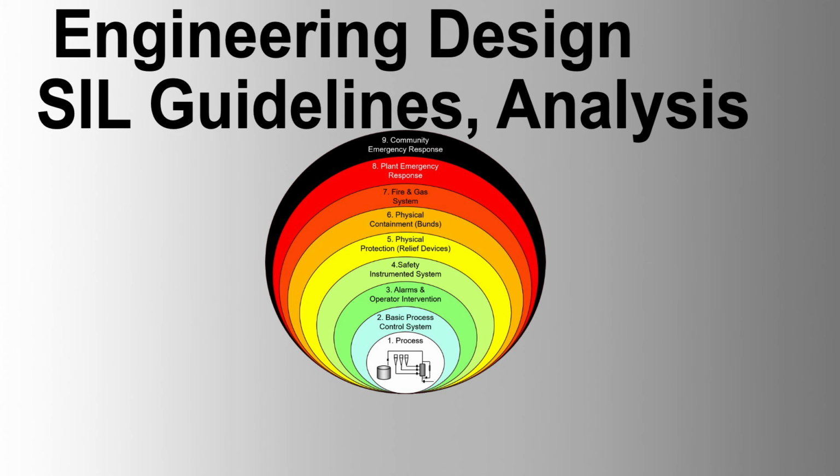5. Quantitative evaluation of fault tree. Use failure rate data to quantify the fault tree. This involves using Boolean algebra to calculate the PFD and the MTTF spurious. Conservative failure rates should be used for SIS components to ensure a higher estimate of PFD. Generate a cut set report to identify critical failure pathways.